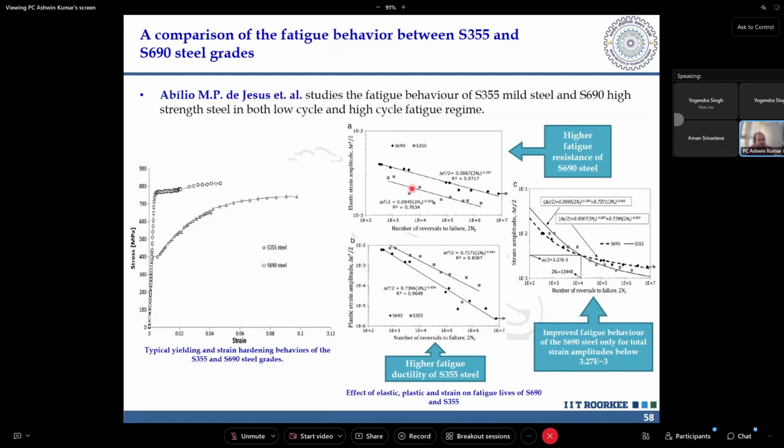that if I use a high strength steel in my bridges, it becomes a lightweight bridge, which means the fluctuation of stresses will be higher than what earlier was. The stress range is going to increase. If I cater my section size with respect to that, then I'm getting a higher fatigue life if I go for a high strength steel.